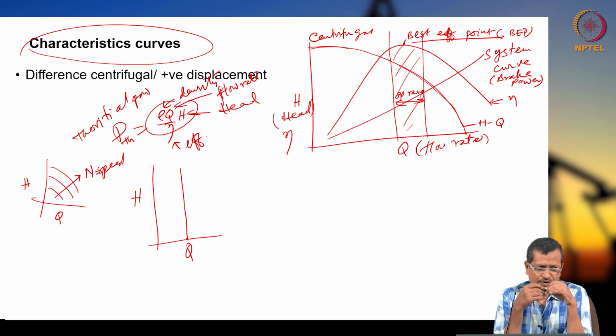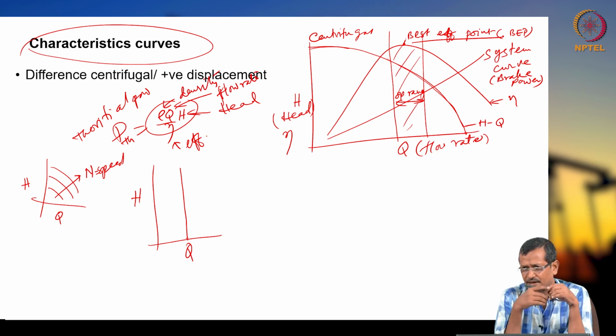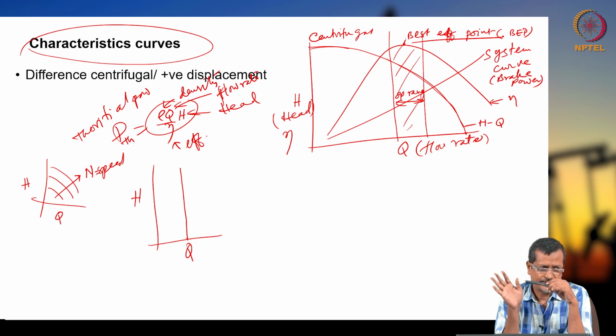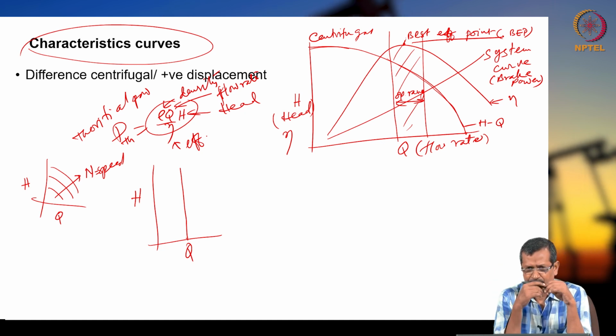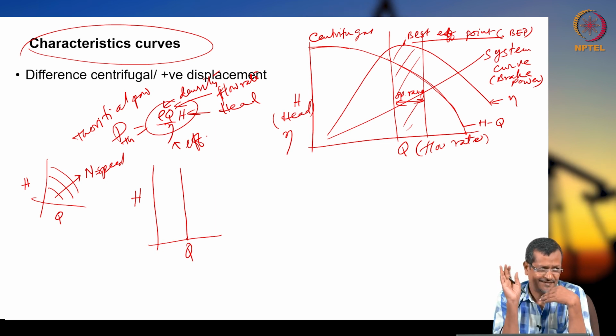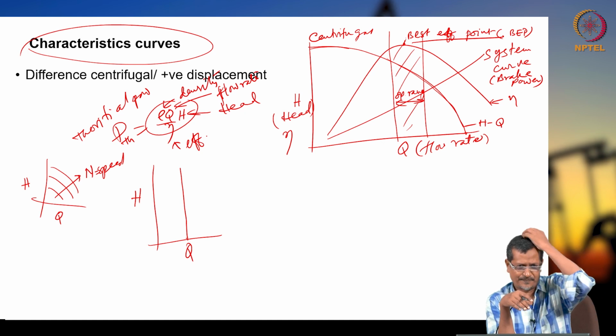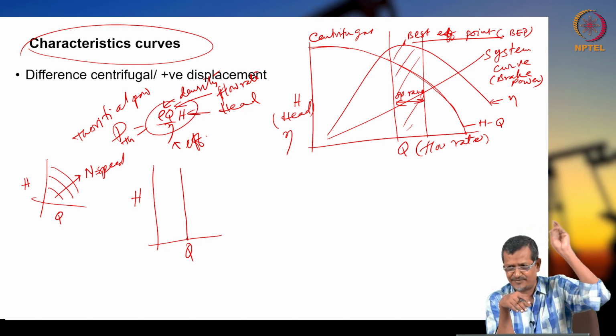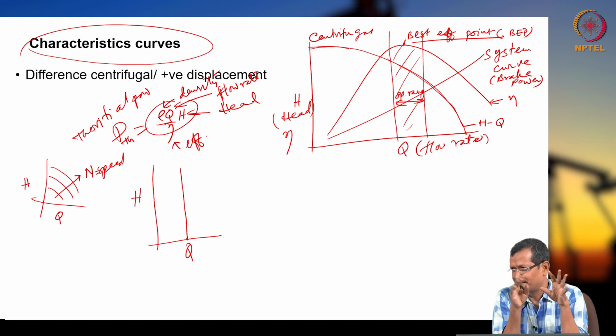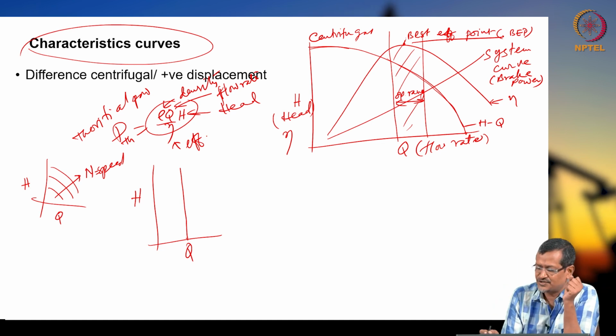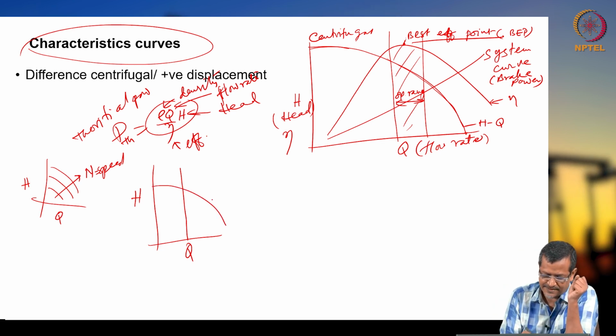Say you take a certain reciprocating pump and you keep the speed the same. When you keep the speed the same, it can raise infinite head, infinite pressure. Any 100 floor, 200 floor, 1000 floor water lifting, a reciprocating pump can work, but a centrifugal pump cannot, because you can see the HQ curve in a centrifugal pump, it is like this.